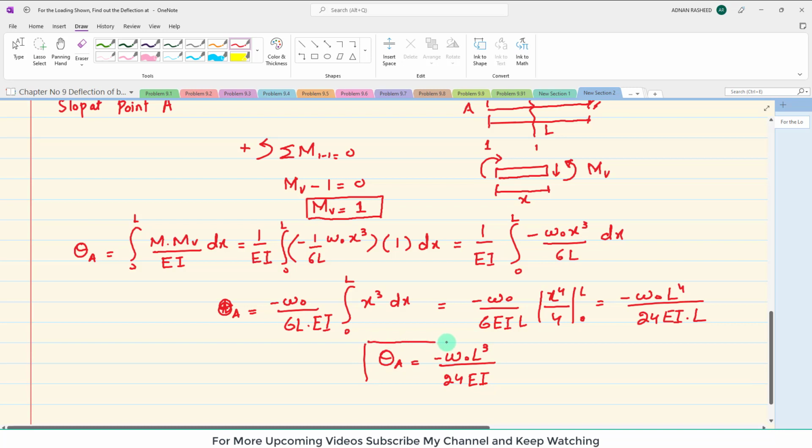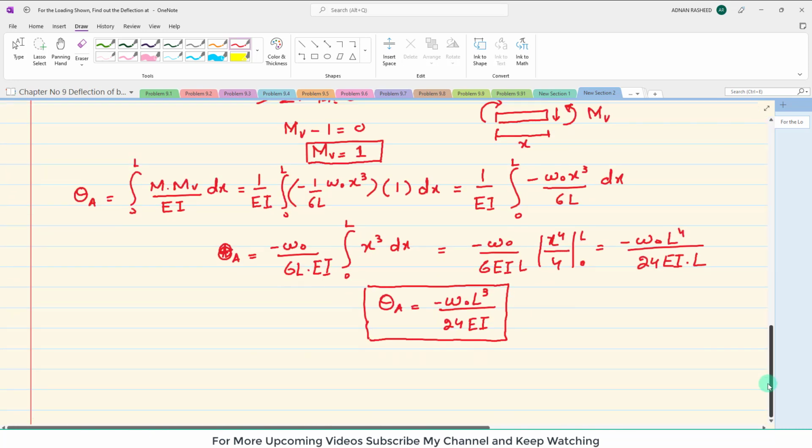So you can see that the value is negative. Negative means clockwise. So here you can see that if you have a cantilever beam that is acted upon by a uniformly increasing load, definitely it will bend like this. Clear? So this slope theta A is counterclockwise.